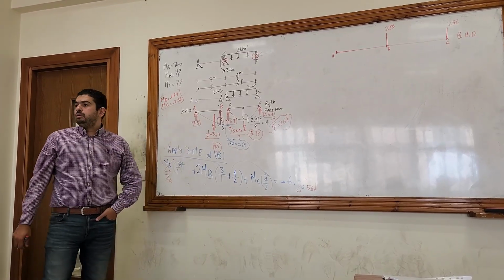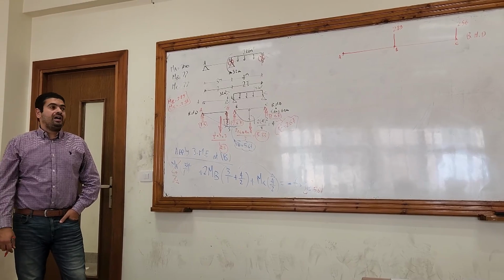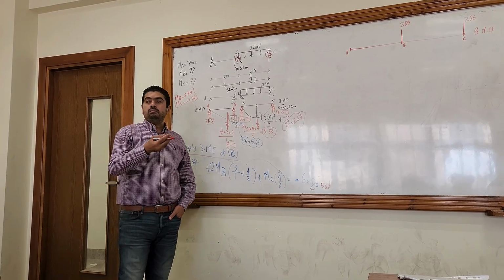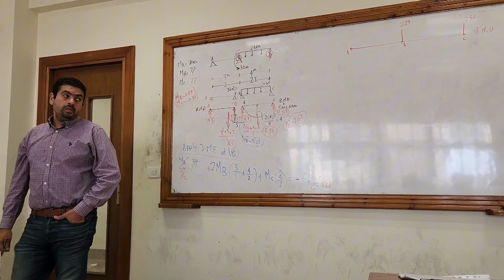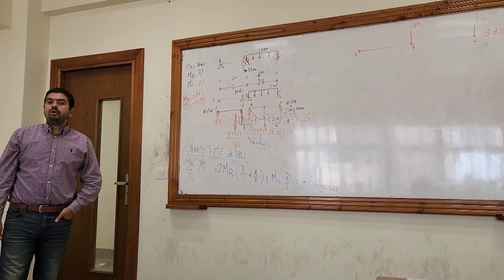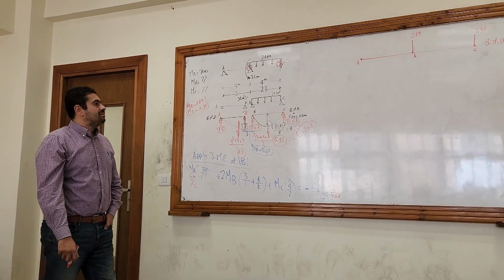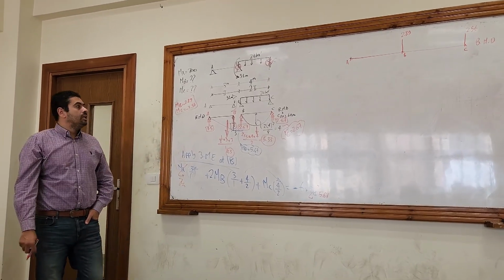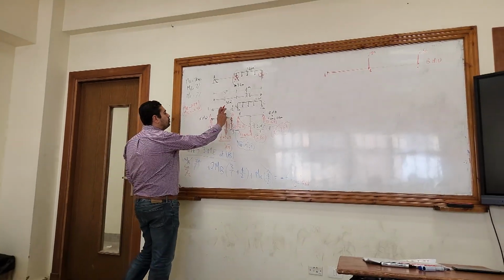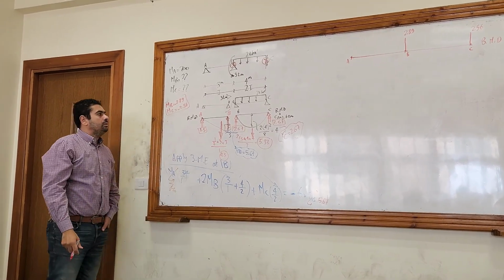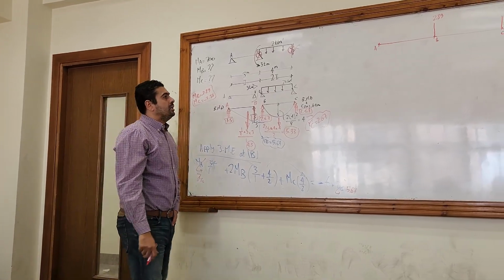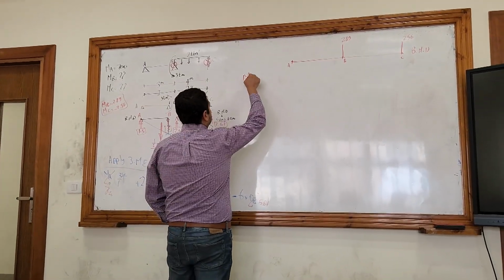And once I know what direction it is, I have to calculate the moment in the other direction, and then I can do the bending moment diagram. So the first question, the 2.89, is it MB right or MB left? It is the moment from the side that you did not put the moment at. Where did you put the moment? On the span AB, which is left. So the MB here is MB right.